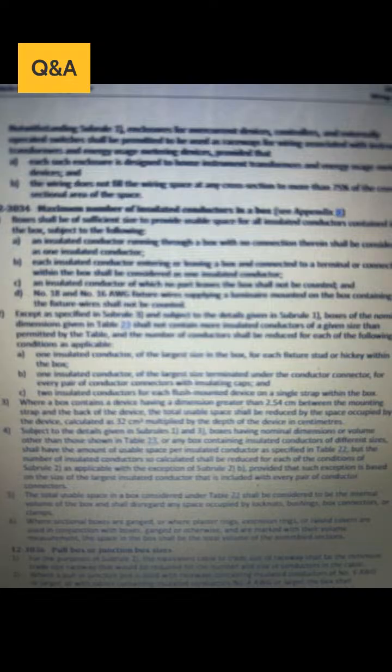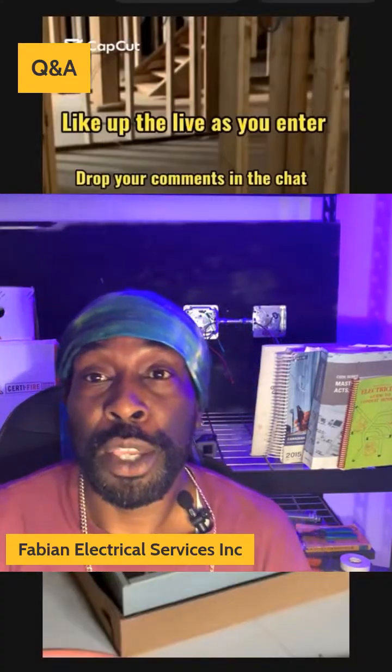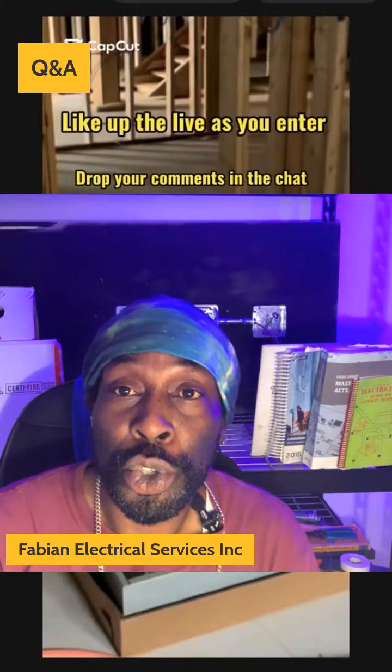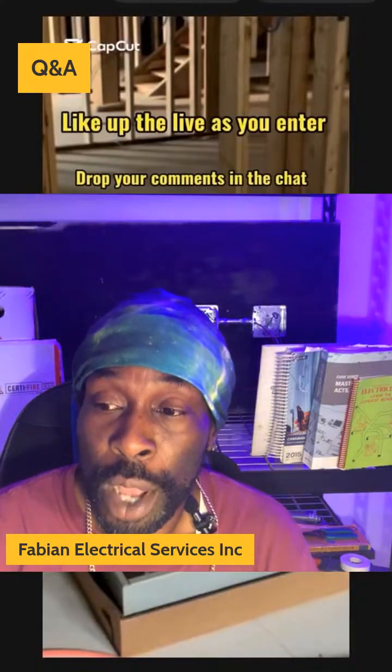And this is another rule, like I said, 12-3034. That is the main rule for the live stream. So what I'm going to do right now is I'm going to take that off. So again, the main reason why you do not cram your boxes is because of overheating. You do not want your wires to overheat, cause fires, and so on.